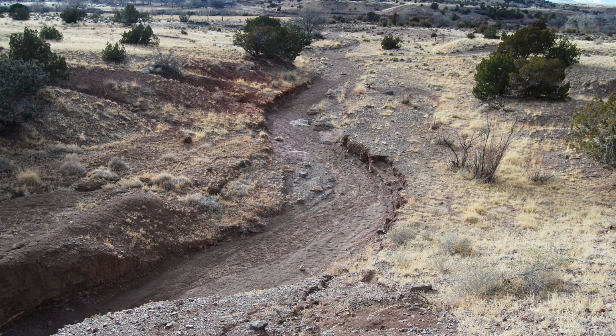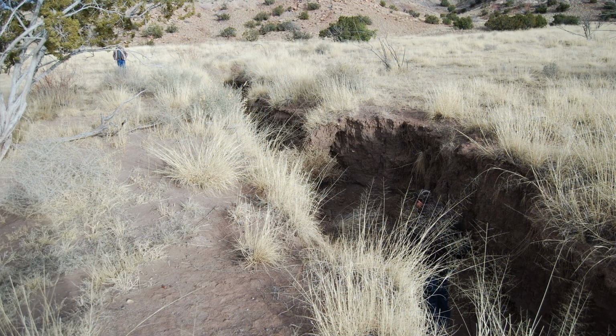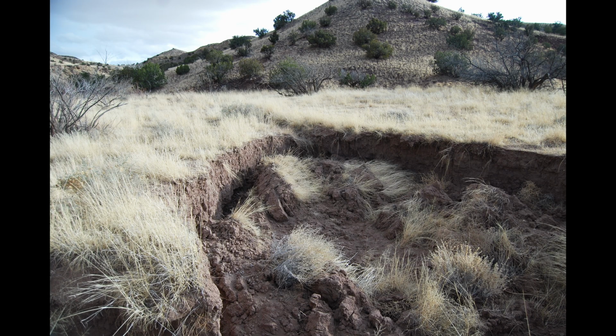Water in the spillway eventually dropped into the stream, and the stream was also eroding. The spillway constructed for this pond was narrow and it dumped water on a steep 10% slope that was not armored with rock. The dam built for the pond had blocked a large watershed, and the spillway carried overflow over highly erodible sandy loam texture soil.